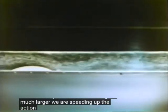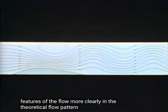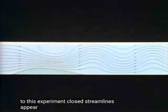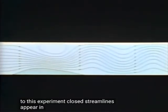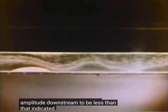We are speeding up the action photographically in this and some later experiments to bring out certain features of the flow more clearly. In the theoretical flow pattern corresponding to this experiment, closed streamlines appear. In the experiment, these regions appear to be unstable and break into turbulent eddies. The loss of energy in this turbulence causes the wave amplitude downstream to be less than that indicated by the corresponding theory.